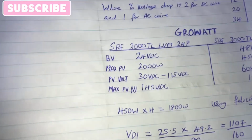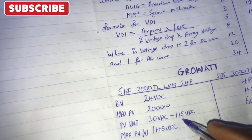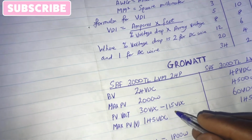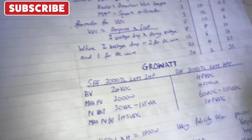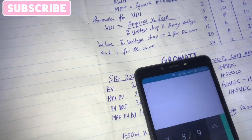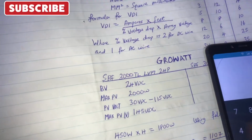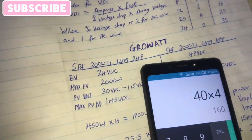The reason why we used 2 in series is because our maximum voltage of PV is 115. So if we say let's connect the whole 4 in series, giving us 40 times 4, we have already exceeded the maximum power. It's going to burn our charge controller.